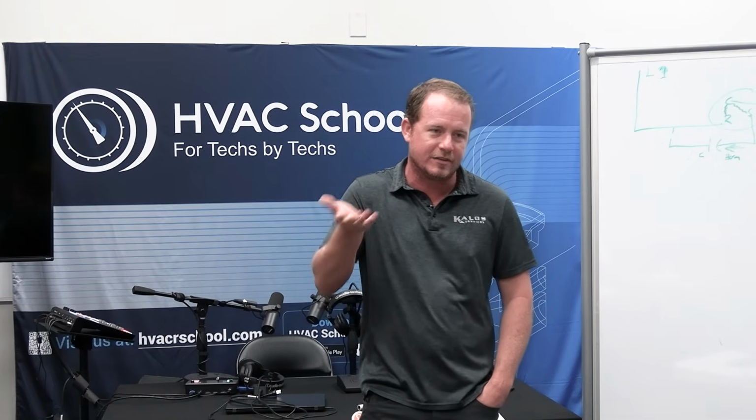A lot of people will say, this is another goofy thing, they'll be like, oh man, if you disconnect a capacitor and you throw that up, that thing stores thousands of volts. It's like, no, it stores whatever voltage it was connected to when you disconnected it. It doesn't somehow boost up the voltage some crazy way. People get confused because a lot of times capacitors are involved in inverter-driven systems that have higher voltages intrinsic to that design, but that's not the same thing as a typical oil-filled run capacitor that we use, or an electrolytic start capacitor. Those are literally just slaves to whatever the incoming voltage is. That's all they do. They store, they discharge, that's it, their whole lives. Nothing else fancy going on there.